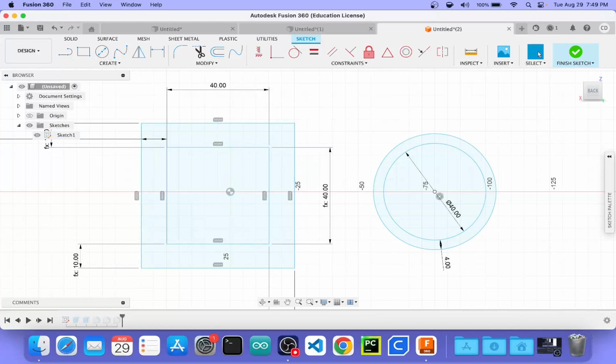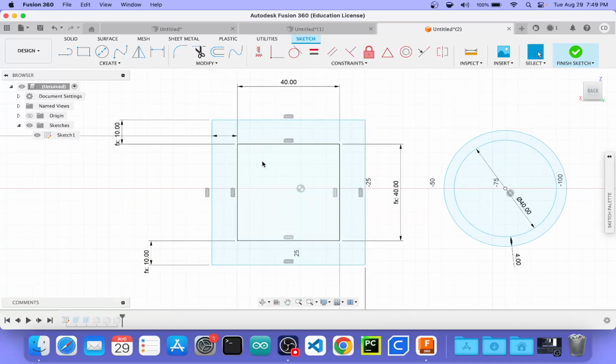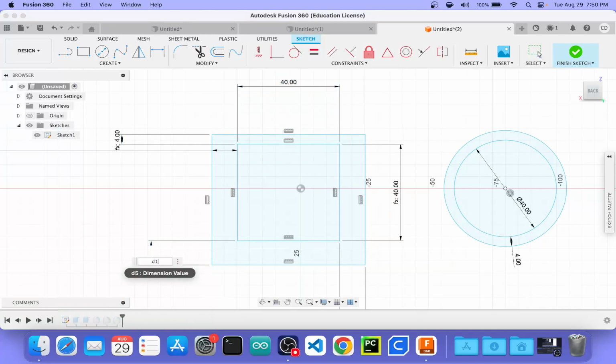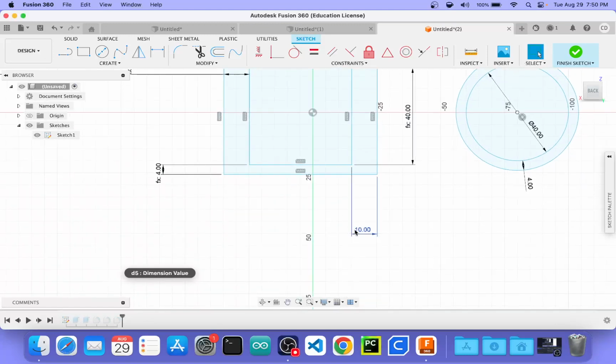And let's say I always want my wall to be 1/10 the thickness of the interior space here. So this is D1. This is the one I'm actually setting. So I can make all of these distances between these two lines a derived distance. And so I can say I want this to be D1 over 10. And I can say I want this to be D1 over 10. I'm going to do the same thing for all of these. Not that one. All the wall spaces.